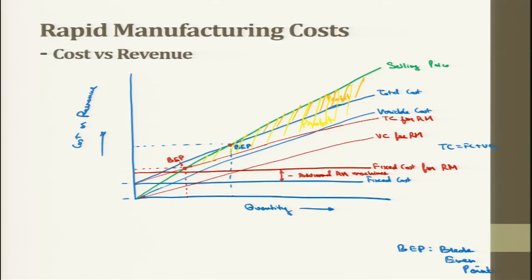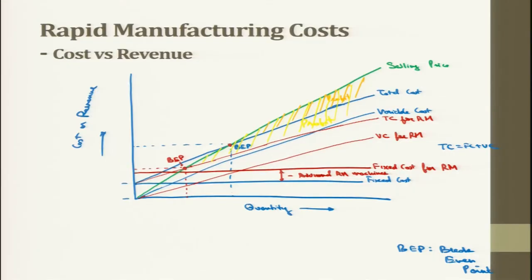So this is how cost and revenue are related to each other in any manufacturing concern. Break-even analysis or break-even chart is very commonly used, but this is a very common model. It has certain assumptions: that any product that will be produced will be sold. So we are considering that any product that is produced here, it has variable cost, those will be sold to the market, number one. Number two, the variable cost is almost a constant. It is a straight line here. In reality, the variable cost also varies. There are certain factors that come into play, but this is a very simplified model.